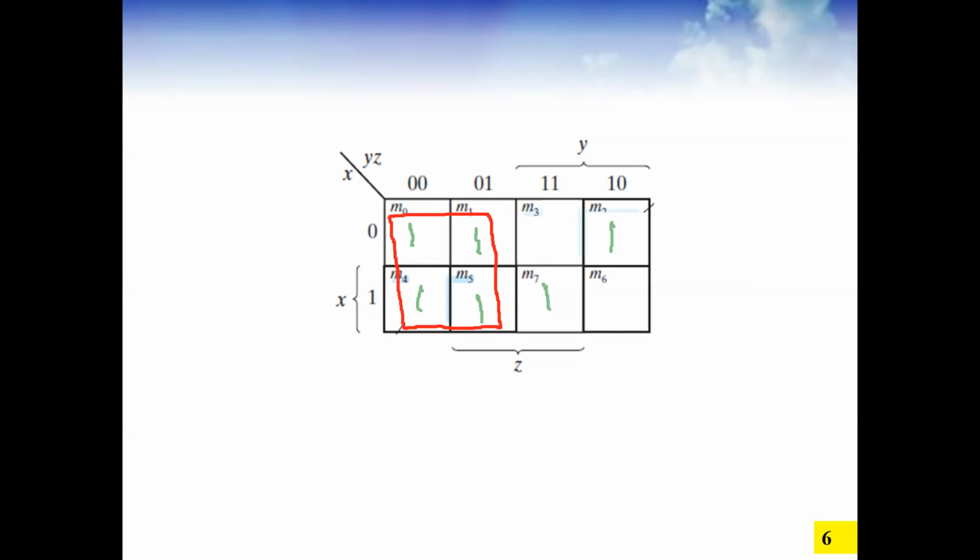So the very first rule is that always try to have a large group. This is the prime aim. Your prime aim is to have a larger group. So for this purpose, if you need to reuse a one which is already a part of another group, you can reuse it, no issue, as many times as you want, as long as you are able to make a larger group. So if you look at this M7, this single one, okay,